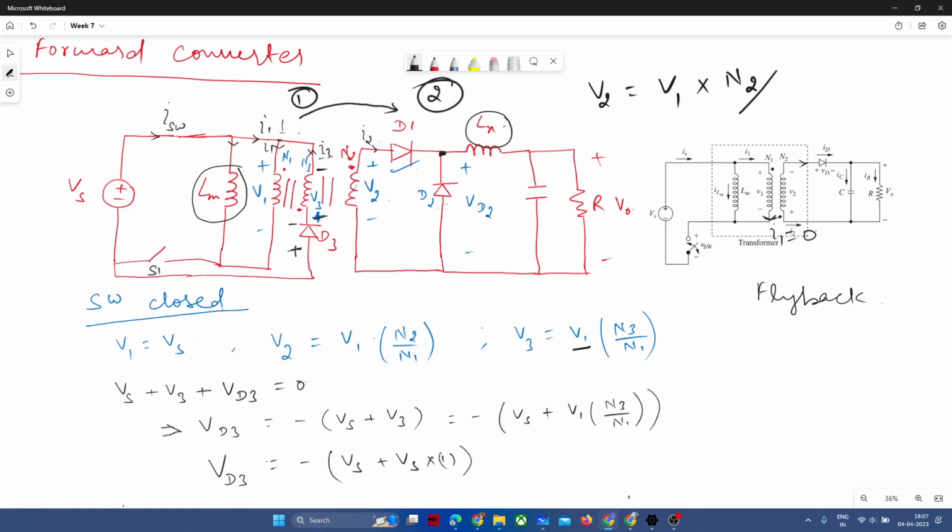Sir, we are measuring the voltage with respect to the undotted terminal. Yeah, from the dotted to the undotted terminal. So we have fixed our voltage reference in such a manner that we take the positive terminal at the dotted terminal and the negative polarity at the undotted terminal. So it will be transformed, but the dotted terminal where it is getting transformed will always have the same polarity of voltage as was earlier in the previous winding, the side from where we are transforming.